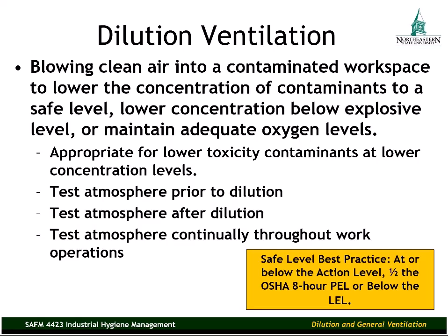And that's going back to direct reading instruments. Or you might perform some type of sampling procedure. But sampling procedures tend not to be as good because most sampling procedures you have to involve a laboratory. It's not a real-time readout. The direct reading instruments are best for this continual monitoring throughout a work operation.